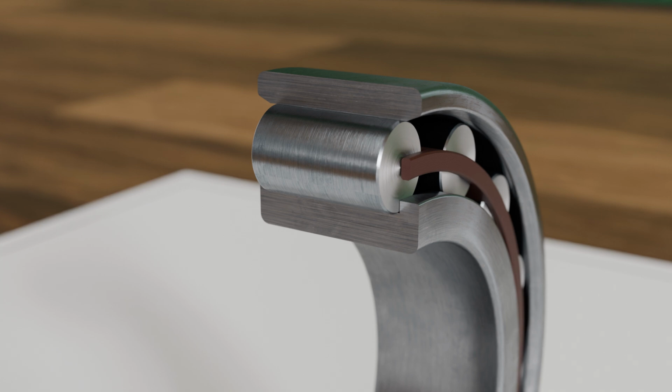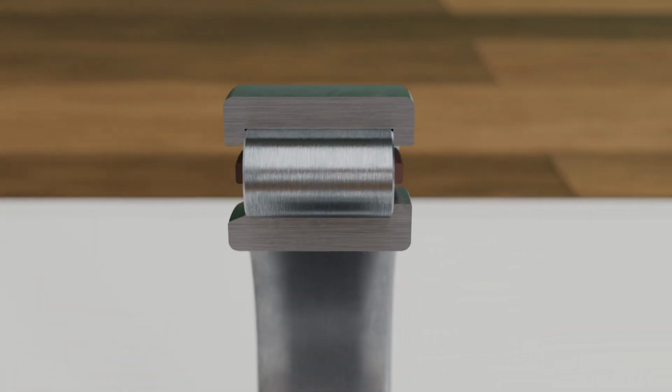Another design of cylindrical roller bearings is the NJ variant. In this type, the outer ring has flanges on both sides, while the inner ring has a fixed flange on only one side. This means the bearing is axially guided and fixed in one direction, but not in the opposite direction. However, the flange on the inner ring serves only for guidance and is not designed to carry significant axial loads.